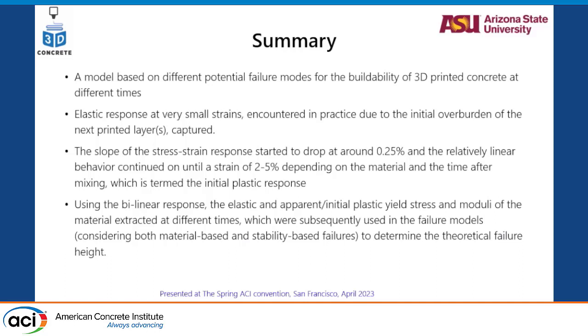So in summary, if we develop the analytical model that could most probably give us an accurate prediction of when the failure will occur, you have a material, you have mechanical testing done for it, then you could most probably calculate the failure height for the structure that you are going to print, and optimize the print time such that you do not exceed that height within that period of time. So you could do a continuous print, maybe a slower but again optimized kind of print. You could stop before a certain failure could happen, so that way you do not lose the amount of work you have done for the printing already.